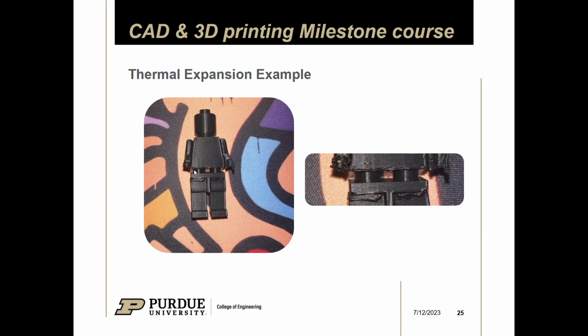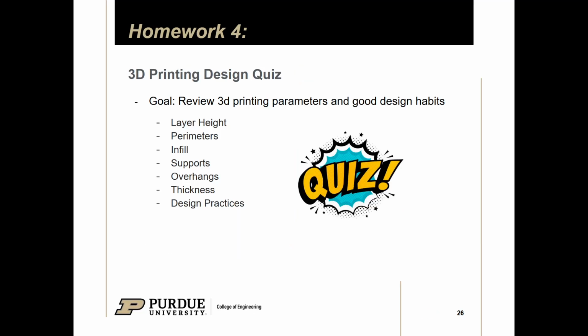So when they tried to put the torso onto the body, or the legs onto the body, it didn't fit because the pins were either slightly too big, or the holes were slightly too small, right? So making sure you add some tolerance if you want interfacing parts is very important, because obviously I don't think this is the result they were after. So yeah, keep that in mind.